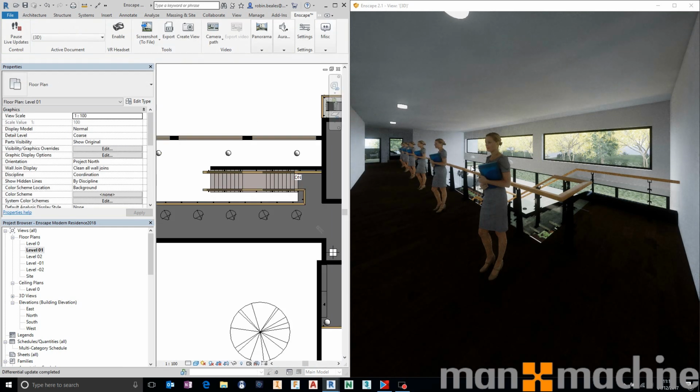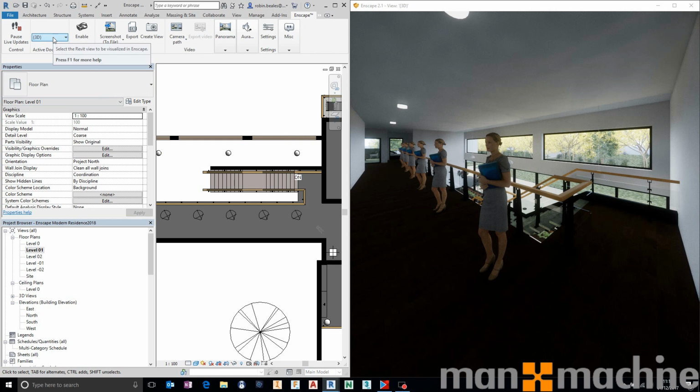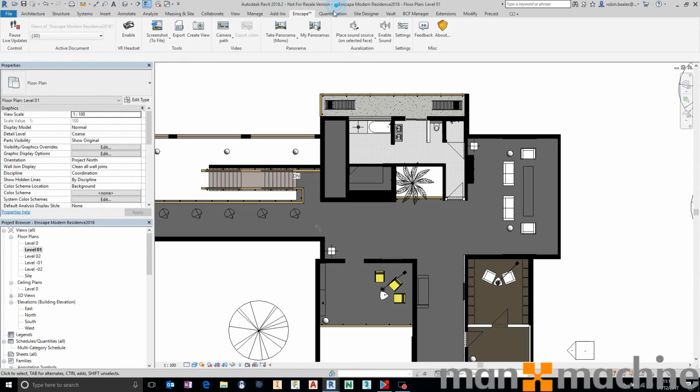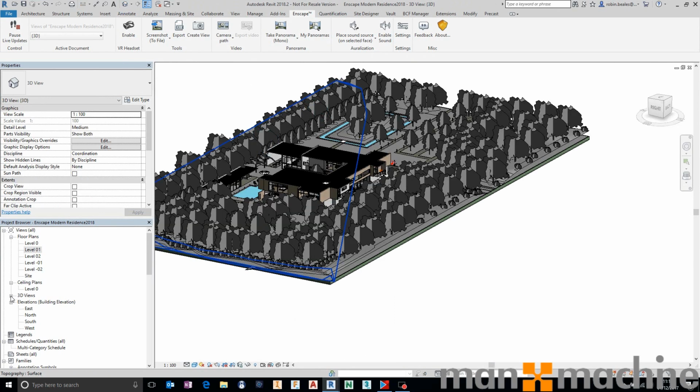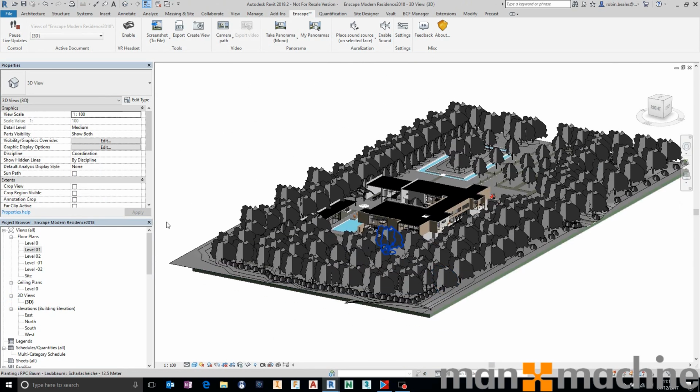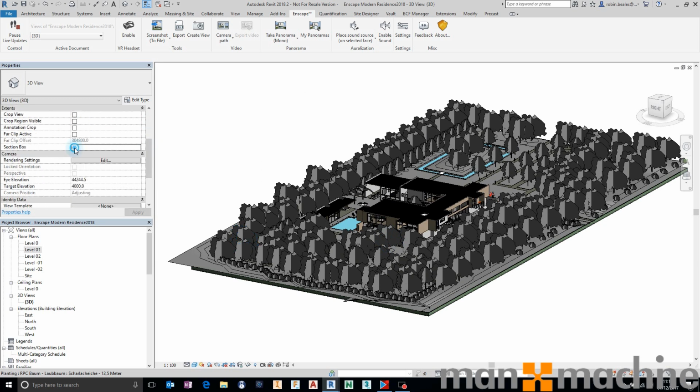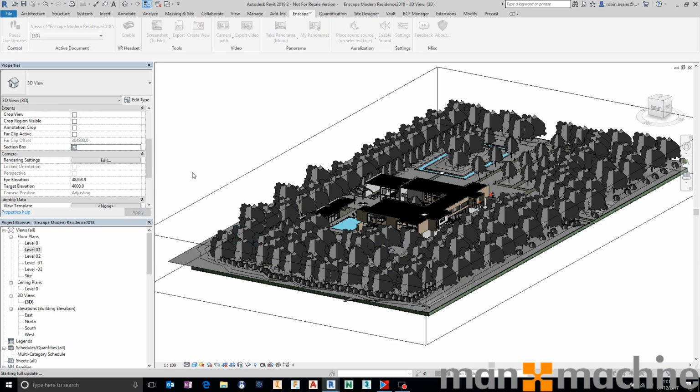Now, the system from that perspective is so easy to use. But actually, again, it doesn't stop there. Remember when I started this, I started it using my default 3D view. For instance, let's just go across into that default 3D view in Revit. So I'm active in the same view. And then using that view, I'm just going to come down and turn on a section box and press apply. This is the coordination side of things coming into effect.